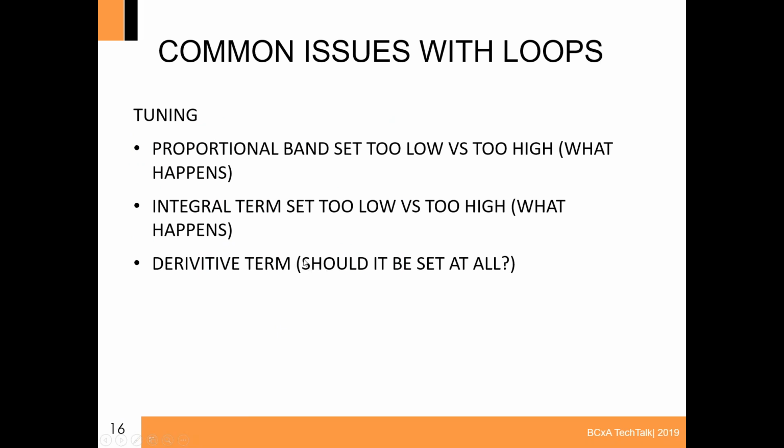That's a very fast changing thing where if you change the speed of the fan, the ductwork pressure changes just about instantaneously, certainly within a second or two. So when you have something where there's very fast changes, that's when you would use a derivative. Pretty much everything else in HVAC would only be a PI control loop.